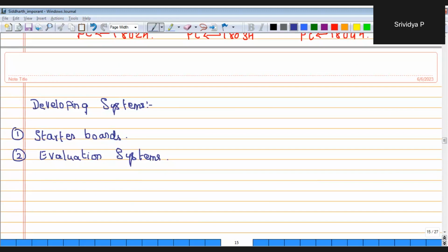These systems will come with assembler software and a serial communication interface for connecting to a PC. Software is provided at the PC side in order to convert an assembly language program to machine code and download the machine code to the memory provided in the evaluation system. The evaluation system allows the programmer to design and build projects of some lower level complexity. The evaluation board can also have internal flash memory or external RAM to accommodate all user programs.